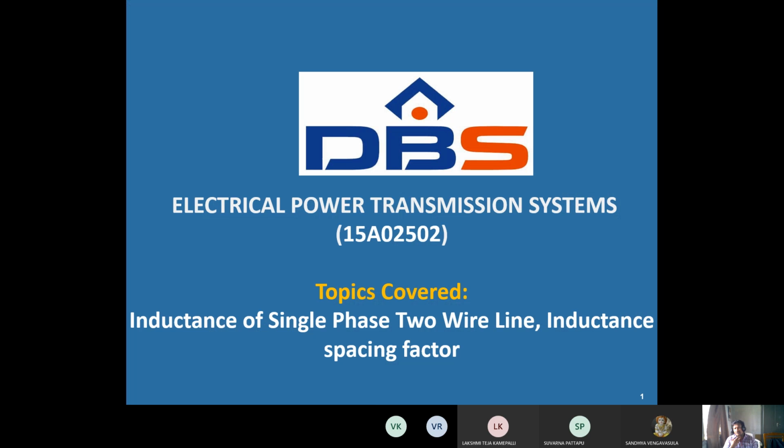Sometimes in problems they ask to find the inductance in millihenry per kilometer. Generally 2 into 10 power minus 7 ln d by r dash, right? R dash is nothing but 0.7788 R Henry per meter. Suppose they are asking to find the inductance in millihenry per kilometer. So many times they ask. So that's why 0.2 ln d by r dash millihenry per kilometer.